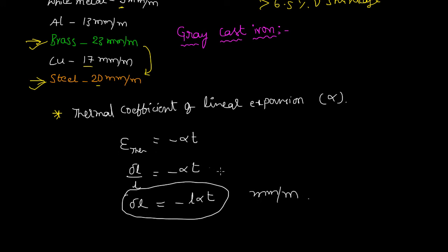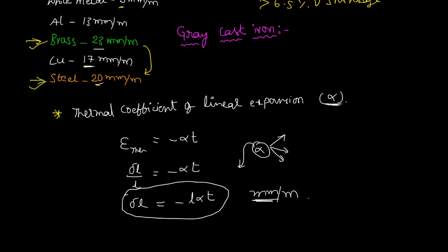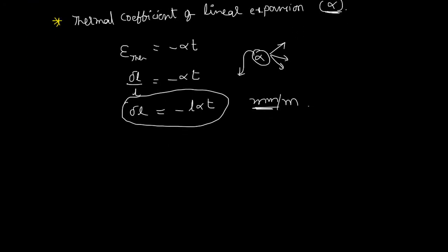For different materials, alpha will be different. For steel it will have some value, for cast iron it has some value, for aluminum it has some value. So alpha decides the shrinkage value, right? If in exam he does not give the direct values of 17 or 20 or 23 mm, then he must give the alpha value. Then only you can calculate the shrinkage value. After that you design the pattern. And there is another relevant point I want to share with you, that is double shrinkage allowance.